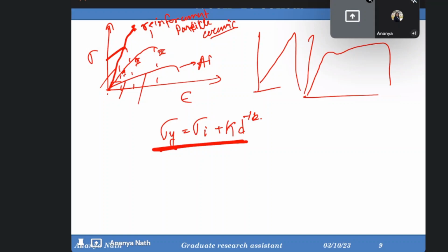Excuse me, ma'am. Yes. Ma'am, I have a doubt here. Actually, sometimes I have also studied in some of the literature, like if the size of the grains is less, means if we are using some nano particles, not micro in size but nano in size. So if the number of particles will be more, means grains will be more, so there will be a grain refinement and strength will increase. But you were telling that will be valid up to a certain limit.